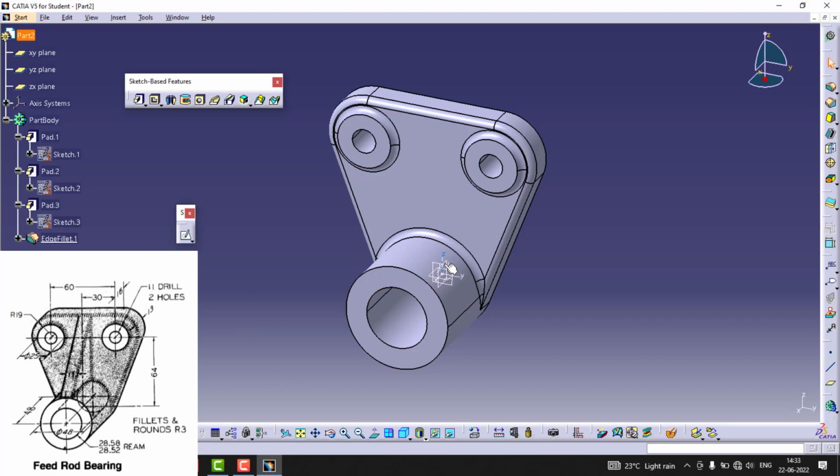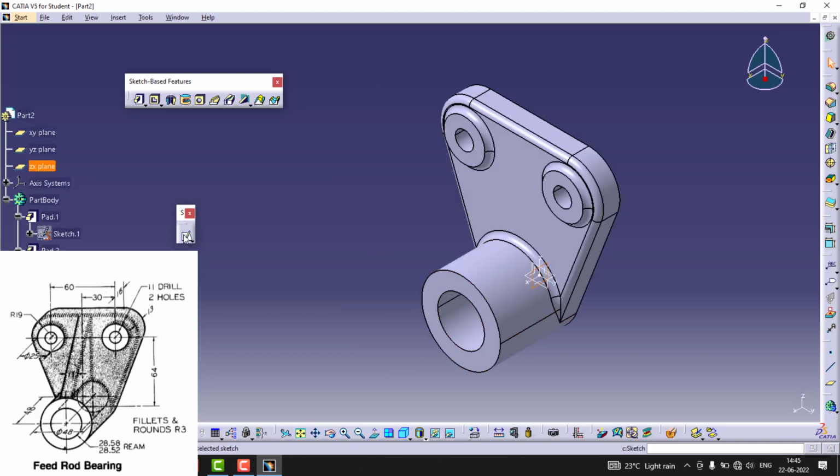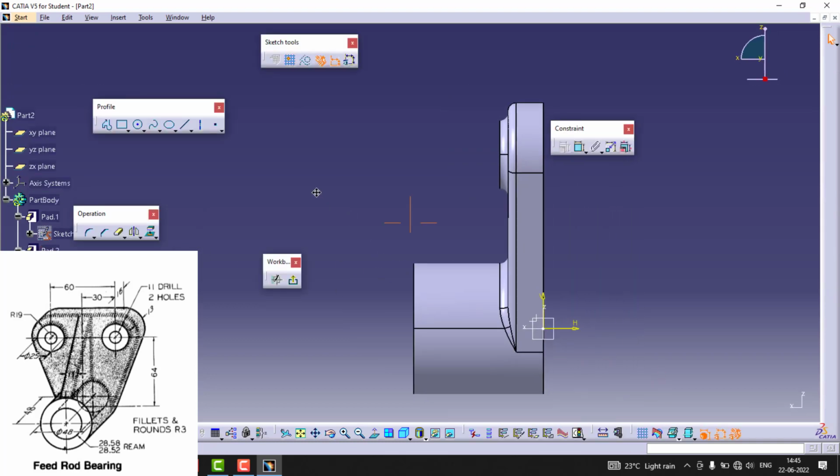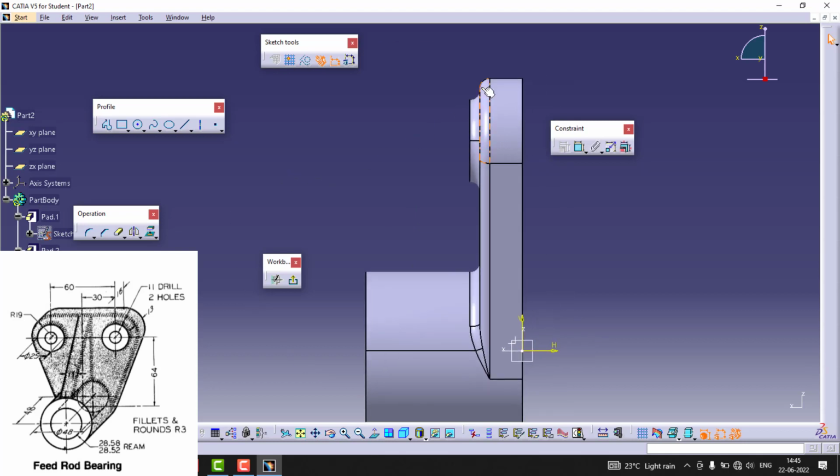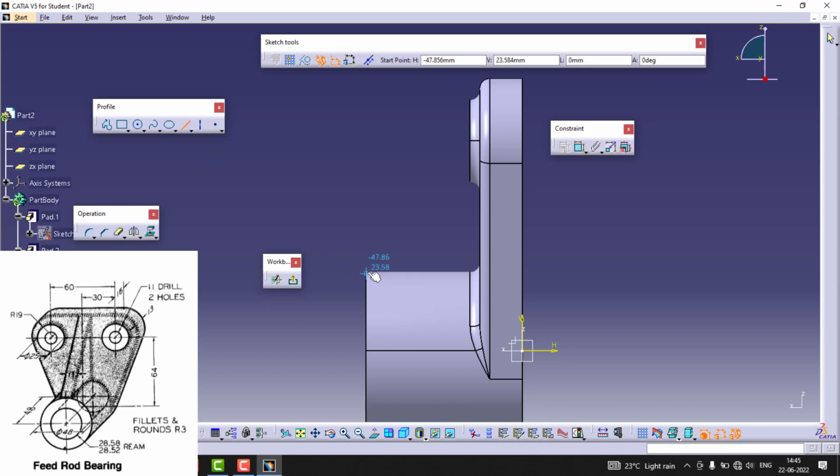Now we can just deal with the same thing, that is creating the rib structure, but you cannot use the rib stiffener here in CATIA as a stiffener, okay, because you have the circular section. It's quite difficult to do that. First thing is I'll snap the references. Let me just draw the rough sketch.